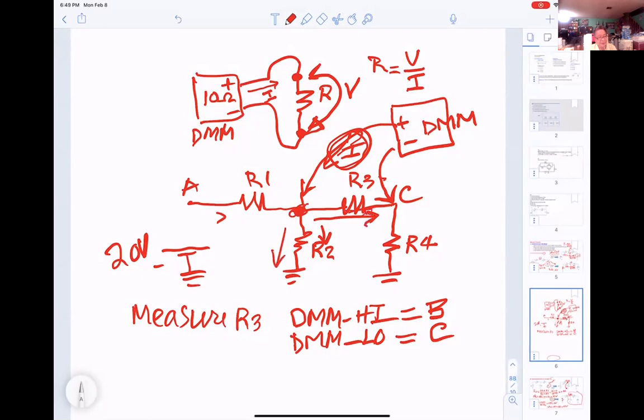So that means the current is not the DMM1 current. So after they measure the voltage across R3 and use R equals V divided by I, you get a wrong I. Then the value will be wrong, and the voltage also. That's what I'm saying.